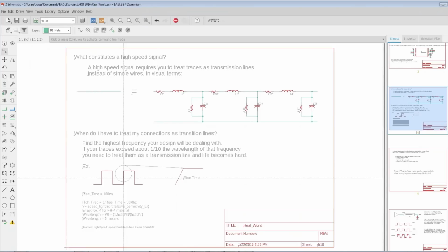Do I have high-speed signals in my design? Once you can make that determination, then you know if you have to go through the concepts that we're going to deal with now, or if the design is basically transparent and pretty much any route will work, okay? From the signal integrity point of view. Obviously, with high power there'll be other considerations, but from the signal integrity point of view, the first thing you need to do is determine, do I have high-speed signals? Am I in the high-speed regime? If I'm not, then I can relax a little. If I am, then I have to be very careful.